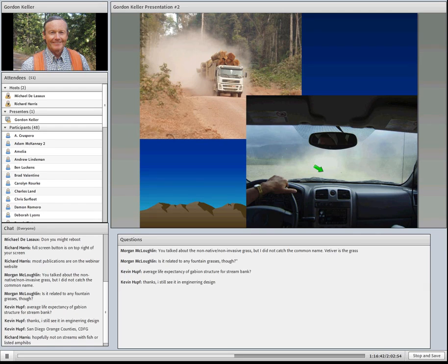There's three problems basically with dust. One is, it's unsafe. You're breathing it, or you can't see where you're going very well. It's hard on the environment. They say billions of dollars are lost in agricultural production because of dust along roads and areas. And it's also hard on the road, because if it's dusting, you're losing the fines that you want to have in your road mix to keep the road surface tight. So it's damaging in a variety of ways.